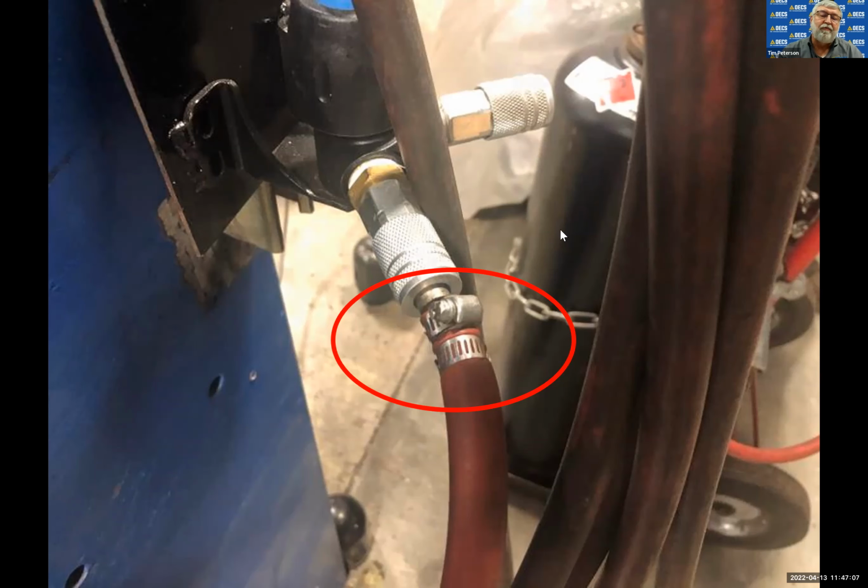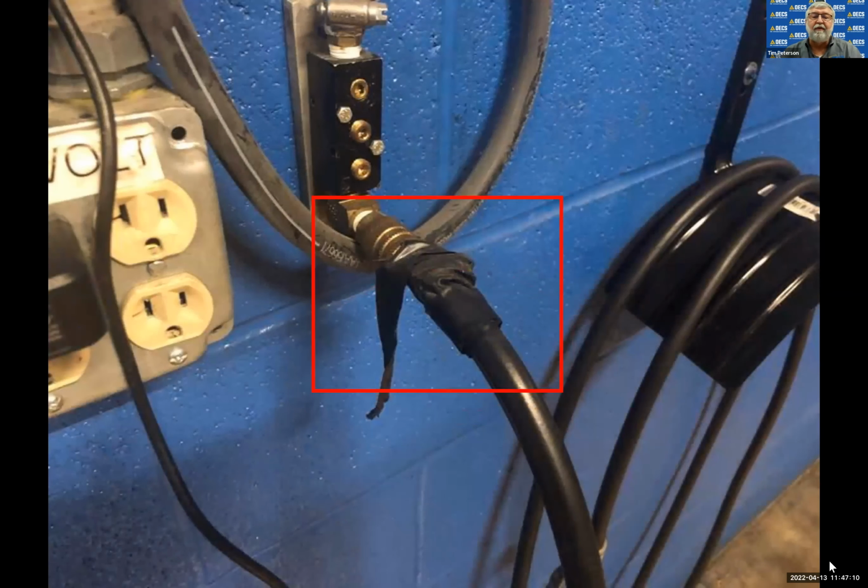And if you tighten it too tight, as you see here, it cuts into that outside insulation. The other thing that happens a lot with electrical and different systems is they use electrical tape as a quick fix. And electrical tape is not to be used for that by any means whatsoever. If you can see here, the electrical tape is coming loose. As I always say, when electrical tape gets warm, it comes loose. When it gets cold, it comes loose. And so it's not really in good condition whatsoever.